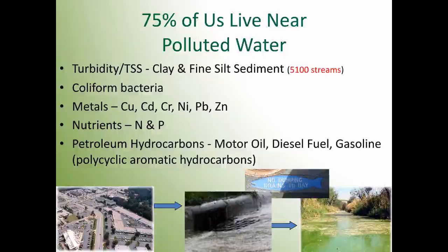According to the US EPA, 3/4 of all Americans live near polluted water bodies. It's not the only reason, but it is in large part because of what I described in the previous slide. The number one source of water pollution in the United States the previous year, and really every year that the US EPA records this, is sediment. It is the number one source of water pollution in the United States. And it's not just any sediment, it's really the fine sediments that lead to water quality impairment. It's those sediments that come from clays and fine silts that really stay in suspension, that lead to high suspended solids and turbidity, or really the cloudiness of the water.